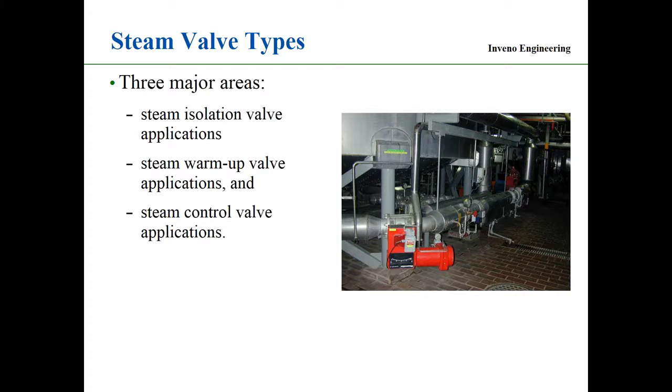Another one that's big in the steam system is steam warm-up valves. Any valve that's 3 inch or larger, we have to have a steam warm-up valve to warm up the system slowly. So we want to make sure that when we shut the main isolation valve, the warm-up valve is also in the off position and not leaking through. So we want to test the warm-up valve.